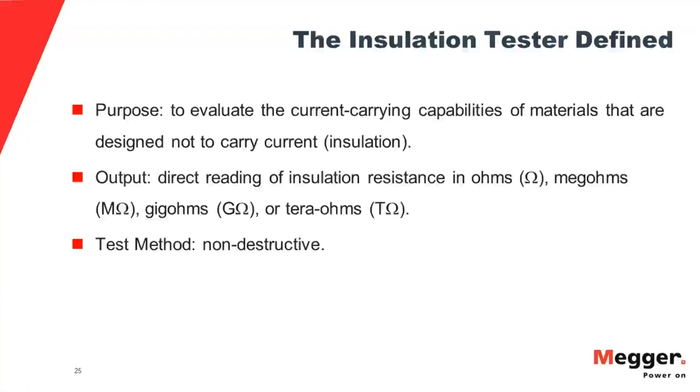In order to measure insulation, you need a lot of voltage, but you do not need very much power because there is very little current involved in an insulation test. If there's much current passing, that's telling you that it's not insulation anymore. So you don't need very much current to do a good insulation test.